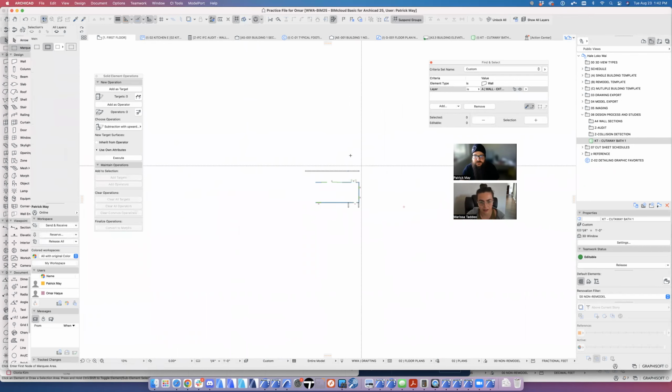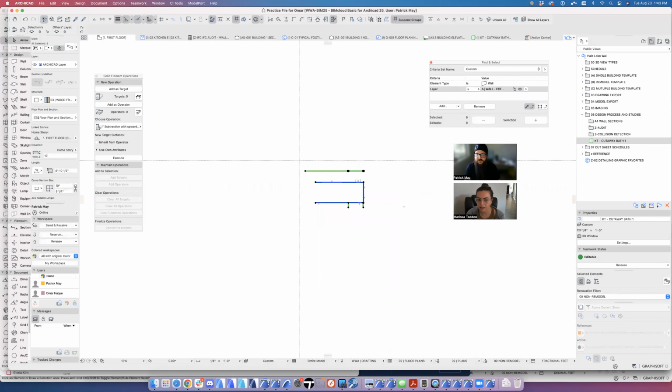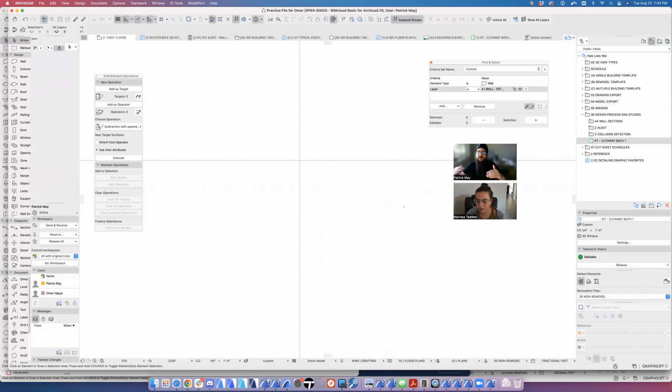If you're using the marquee to stretch something out, even if you know for a fact that everything above and below needs to be stretched, I still use the light marquee and stretch this over say 5 feet, and then just go down a story and repeat the process for each story. That way I know I'm not messing up any of the site contours or site walls, because it's very likely that a lot of these projects will have extra stories below or above just for burying stuff, and then that stuff gets thrown off, or you're not aware that a layer is on that other story because there's nothing on that layer on the current story.